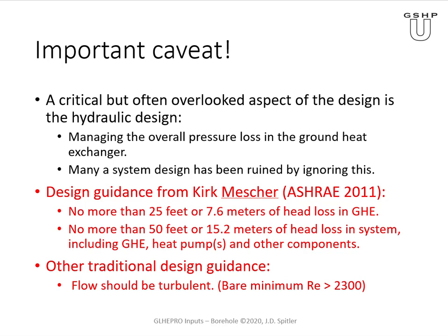You can take a ground source heat pump system, which is an excellent concept, but if you design the piping, and this could be the piping in the boreholes but also the other piping, and you put in a bunch of valves to balance the flow, and you have a very high head loss, you can completely ruin the system from an energy standpoint.